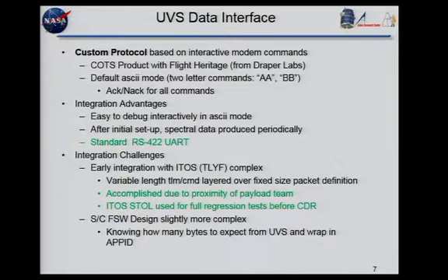So what we ended up having, and another decision we made with these payloads, is I didn't want to have to know what every command to every payload was on board. I wanted the ground to be able to send it up, and I could put some wrappers or do something to it and pass it through. In this case, when you'd send a command, you didn't know what the size of data coming back was, because it had ACKs and NACKs. So I wanted to be able to handle it, and each command had a different length. Rather than putting that into the code, I put that into the API for the command coming up to the module that would say, I'm sending this command, and nominally I'd get back this number of bytes.